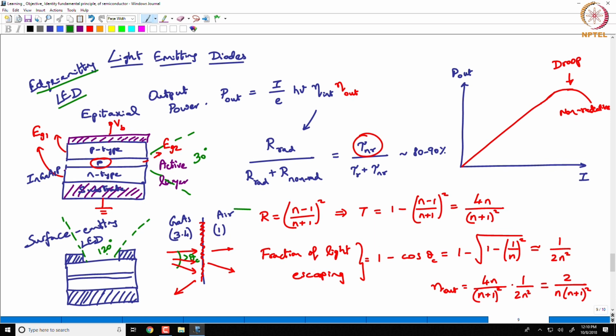So, in this case, you can take an optical fiber and place it at the output of that edge emitting LED, and you can couple a lot of light efficiently into the fiber, because the spatial coherence is fairly good from these sources. Okay. So, edge emitting structures are more amenable to coupling into an optical fiber,